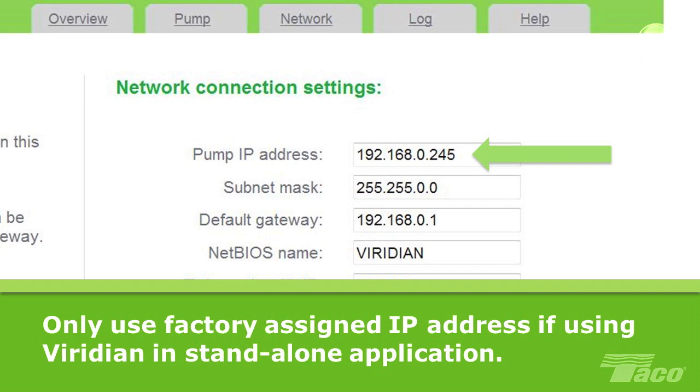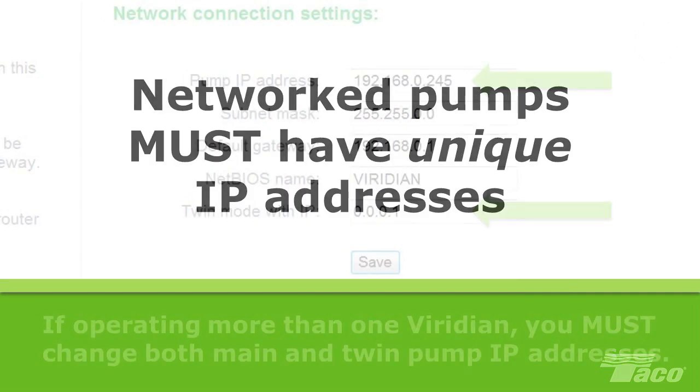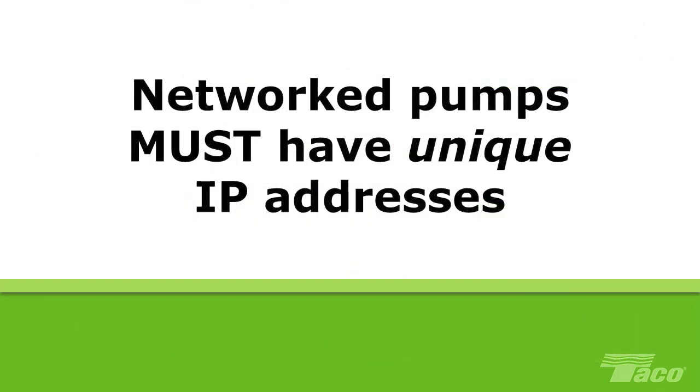However, if you are operating more than one Viridian, such as in a main and standby configuration and/or when the pumps are connected by a wireless router or building management system, you must change both main and twin pump IP addresses. Each Viridian must have its own unique address, distinct from the address of all other Viridian pumps in the system.